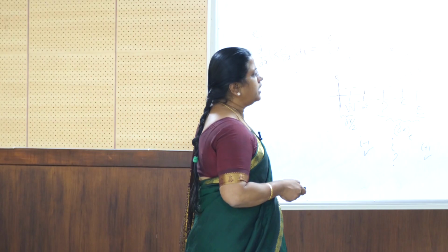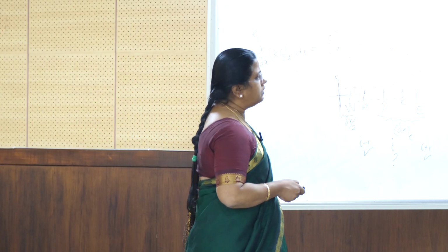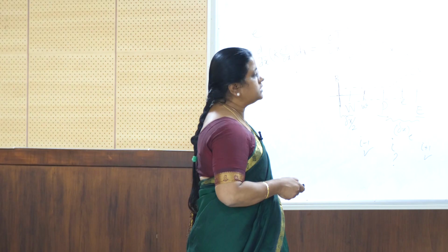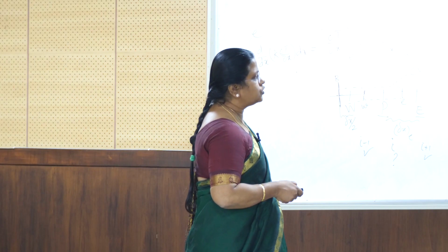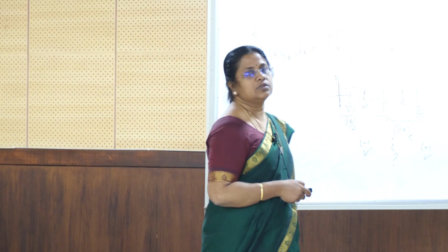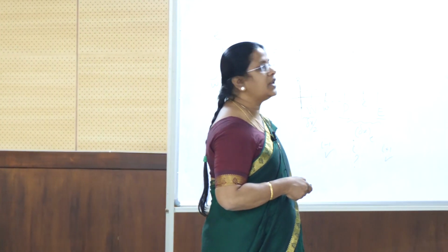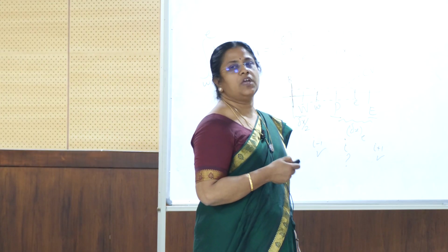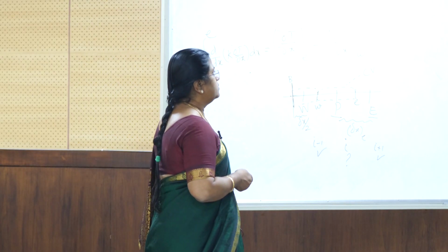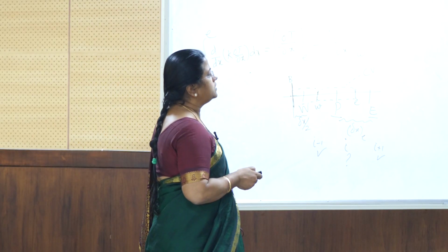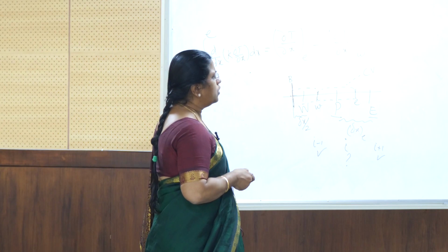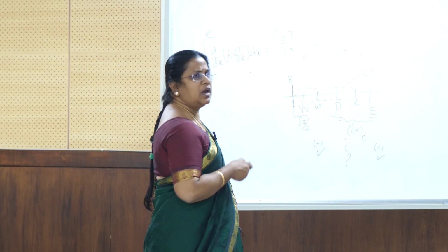How are we finding this out? We have to choose our mesh size of time such that it satisfies this condition. This is known as the CFL condition. How much we have to choose: here this is a constant. So rho C and K are constants, and delta X is the mesh size which we are specifying along the X direction. So this is the fully implicit discretization scheme, and the coefficients are given here like the previous one.